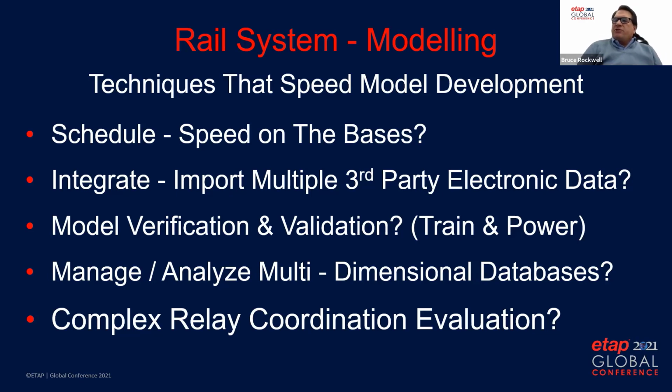And with the integration of electrical and mechanical analysis, the ETAP software allows you to manage and analyze multi-dimensional databases. So in eTraX, we develop a model that's a catenary and rail system model, and then we can use the various modules in addition to the eTraX module, which gives us the load flow. We can utilize arc flash modules, protection and coordination modules, and short circuit modules to analyze multi-dimensional databases.